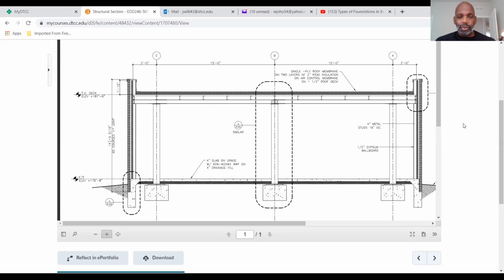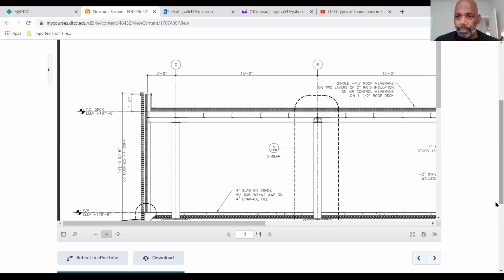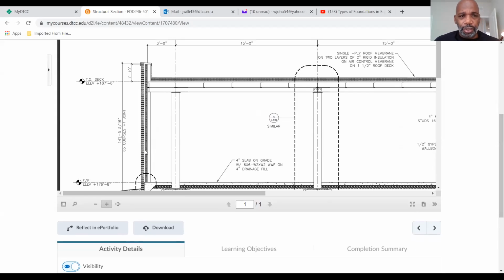All right. So that gives you a basic understanding, and then we're going to be adding this brick veneer that you're going to take from the detail component manager. This is not going to be lines, but it's going to be taken from the detail component manager as I explain it further. Let me zoom in a little bit. Okay, we have some wall insulation here. That's actually a detail component. Detail component here for the insulation. Of course, you can recognize these channels and this S-frame as being detail components. You already have the spacing of these given to you when you created the framing plan.